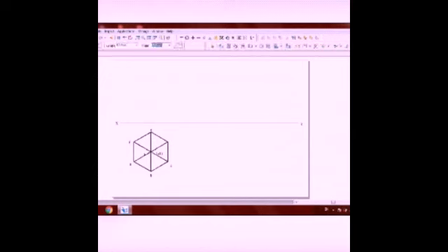Next, draw from the line command, setting the line thickness to 0.13, the construction lines from each of these points. Of course, since many lines coincide, we will have only 3 vertical lines, and preferably the axis line is to be drawn separately so that we can show it as an axis line, that is vertical 60 mm. Take that line and make it an axis line. You draw the lines representing the slant edges to the apex, and unfortunately that axis line is overlapped by a solid line.